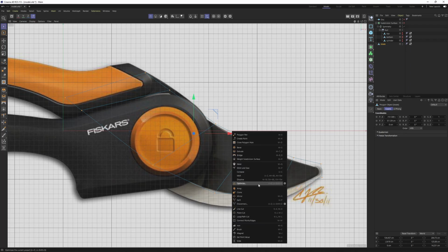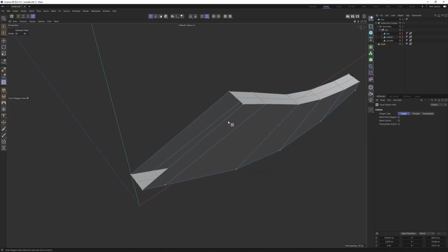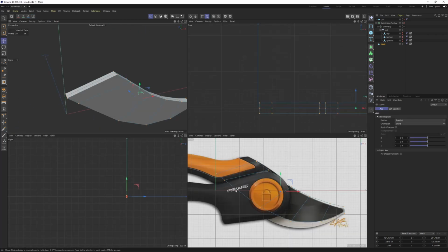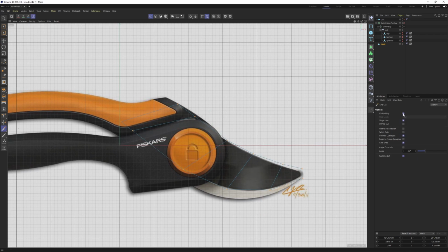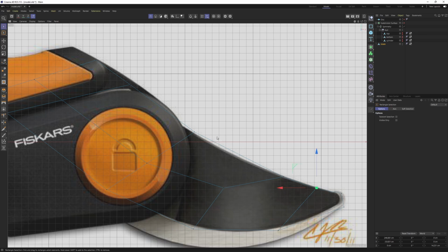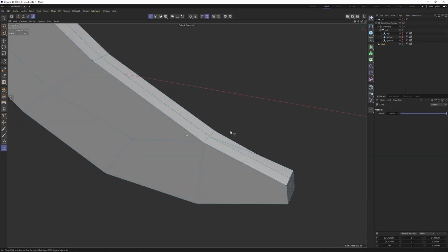First, let's select line cut. Or first I should close that hole with the close polygon hole tool. Then points mode, connect the points with line cut. I will continue with the line cuts. This time though, I will just turn off visible only. Cut here, here. Then I'm gonna stop. Switch to points mode. I'm gonna move these points. Press Ctrl and merge these points.